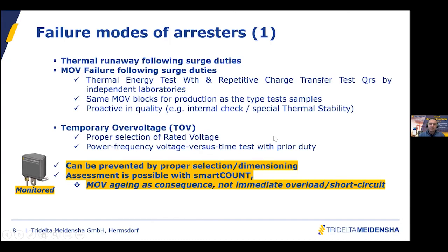So what we want to show here is that the smartCOUNT, the monitoring solution, which has the capability to measure and evaluate the resistive current, can help you to evaluate the MOV aging and to assess the health condition, which are a consequence of those failure modes that could occur on the surge arrestors.